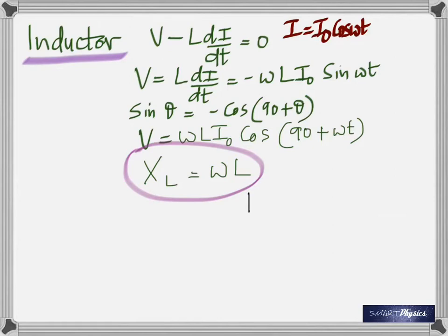Is direct current oscillating? Is it changing? So what's its frequency? So if you apply direct voltages across an inductance, it has no fight. It says, go through. Why? Because omega is zero. But as the frequency increases, XL keeps increasing.